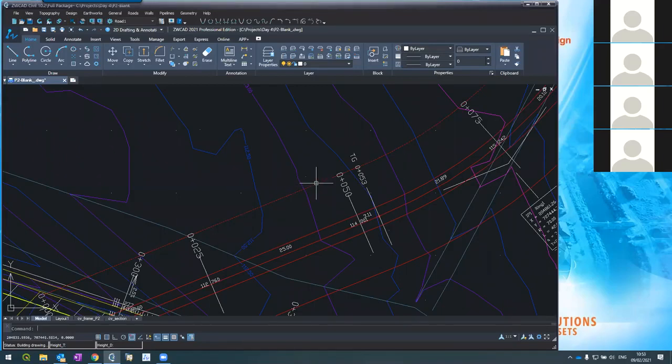Now, I'm using a sidewalk. Here I had shoulders. Here I want to do a sidewalk. To the left is 3.5 meters. Why? It's my decision. And to the right, only 1.5 meters. This is what I want. Okay, so this is my road geometry. From the center line, median till here and here, asphalt here and here, sidewalk here and here. Let me save it.